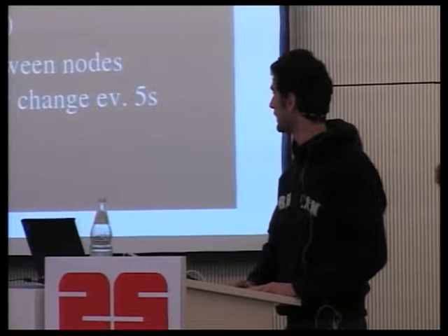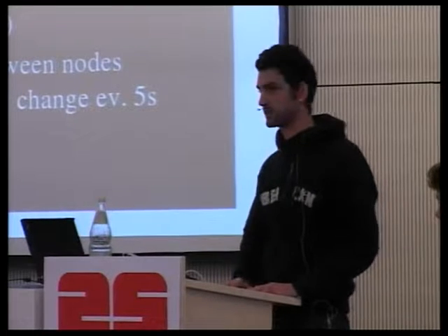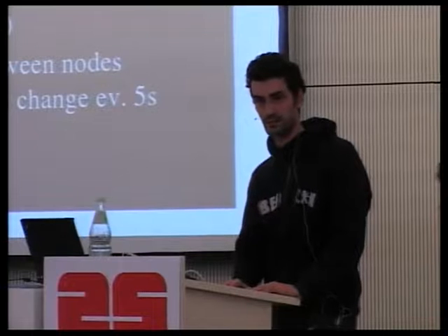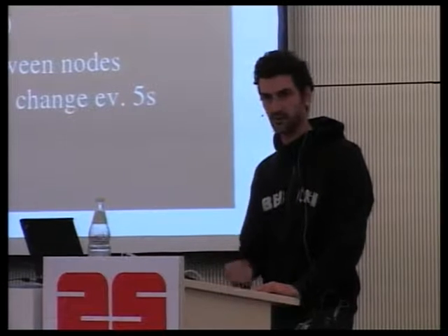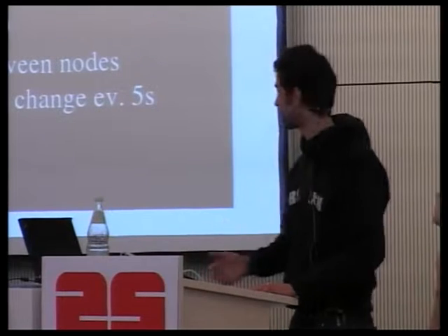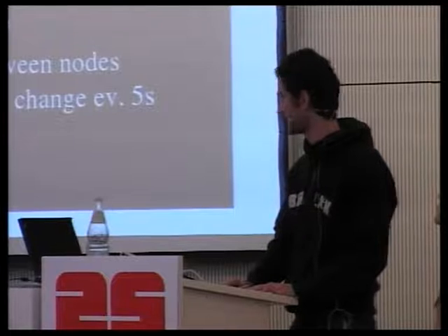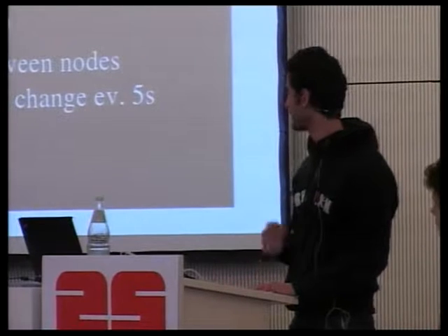So it's not easy, like with a chip card where you can just dump the data and do the decrypting offline. Plus, at the physical layer, like I said, every 5 seconds you have a reconfiguration of the modulation. So if you want to sniff the whole packets, you will have to be able to change the modulation picked by the devices every 5 seconds to be able to reconstruct the bit stream.